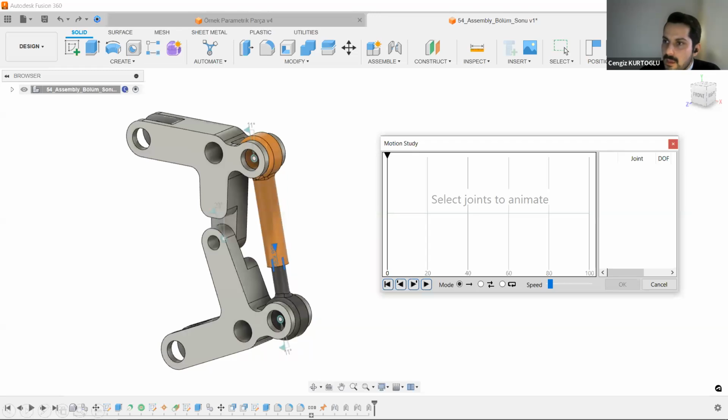Well, there's a question about the parametrics of materials. You can change all the parameters as custom materials. You can assign custom materials on your properties. For example, you already use stainless steel, but you just want to change the Young's modulus as a custom parameter of your material.